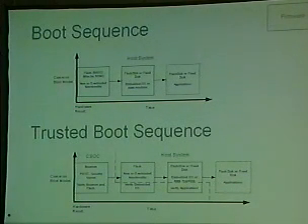Usually what it'll do is it'll verify the boot ROM firmware itself inside of the CSOC, and then if that's okay, it'll proceed to the next thing, and it'll first go out and verify firmware stored on an off-chip device. If that's okay, it'll go out and start verifying kernels, applications, and whatnot. But you can always roll your chain of trust back to the code that's inside the CSOC that can't necessarily be tampered with.